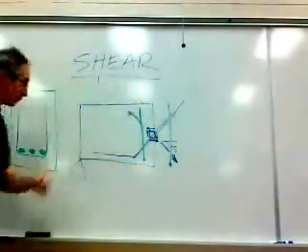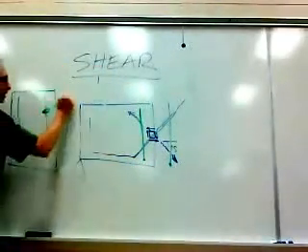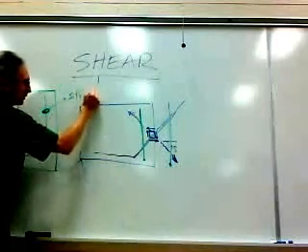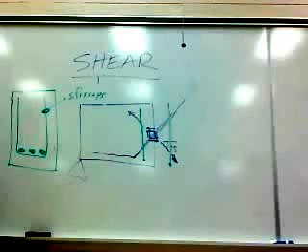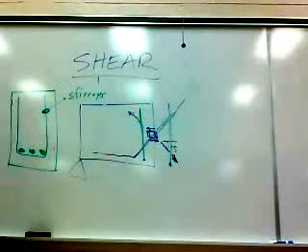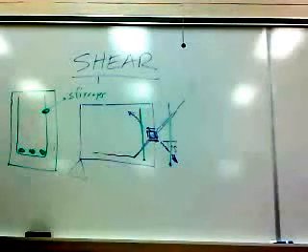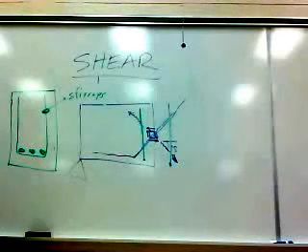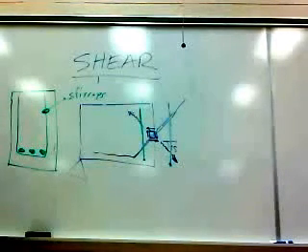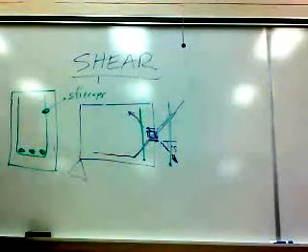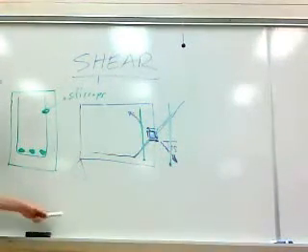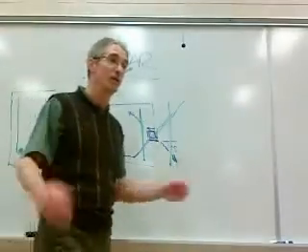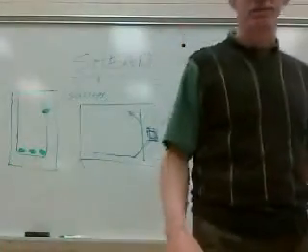Okay? So these U-shaped bars called stirrups, this is the way that we reinforce our beam against shear. All right? So, a little bit of an intro to shear, the behavior we're going to see, and then ultimately how we're going to reinforce against it.